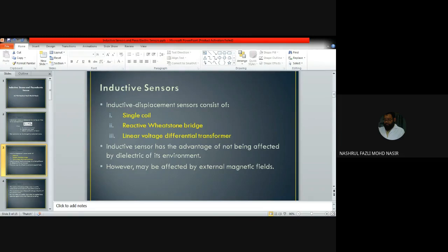So this can be used to detect vehicles and adjust the timing of traffic signals, and it can provide alternating signals at a busy intersection when needed. So this is the good thing about the inductive sensors. But one thing that is not good with the inductive sensor is that it is made from magnets, so it can be affected by external magnetic fields.